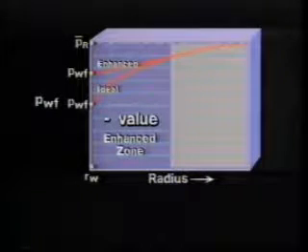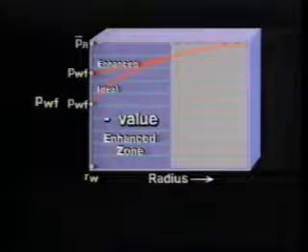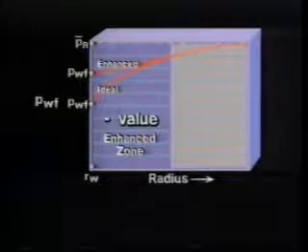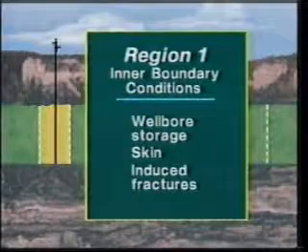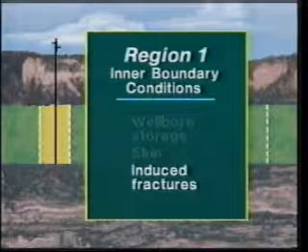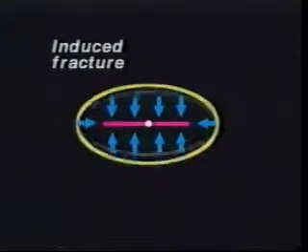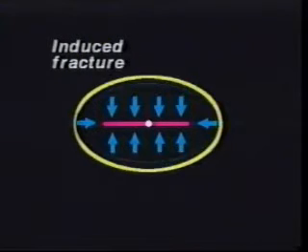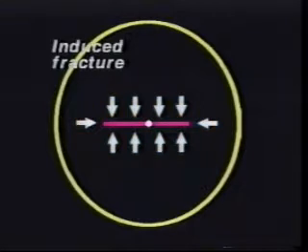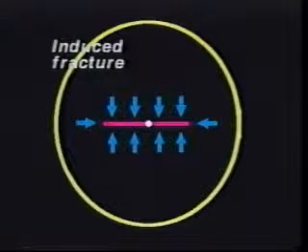Unless the wellbore damage is removed during the test, the skin effect is not transitory, but is present throughout the test period, and its effect depends on the flow rate. The third near wellbore condition is known as induced fractures. A vertical fracture induced near the wellbore, as we see here in plan view, will result in a linear rather than a radial flow into the wellbore for a short period of time after the well is open to flow. In time, the ellipses will become circles, but the early linear flow patterns provide a characteristic pressure response, which we may measure and interpret.